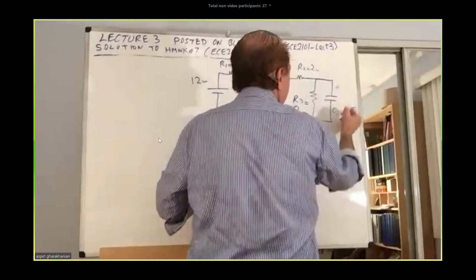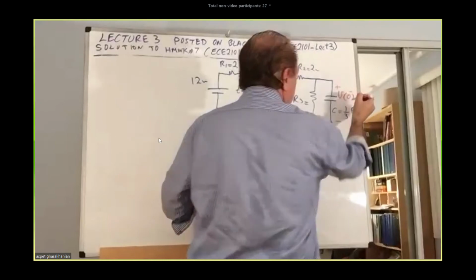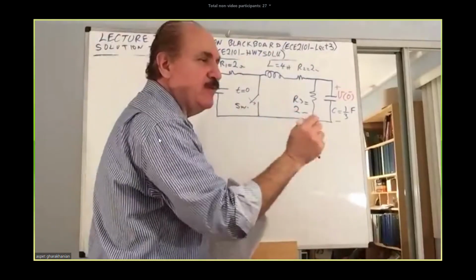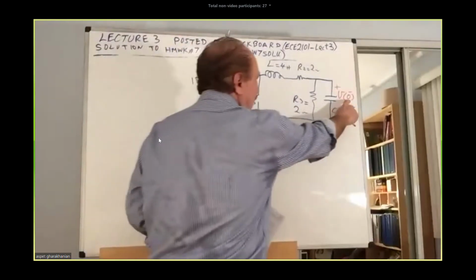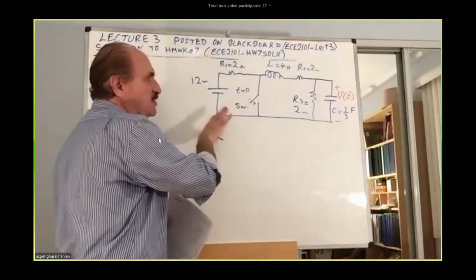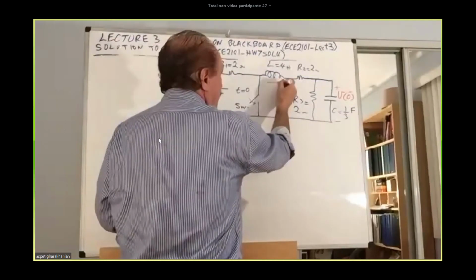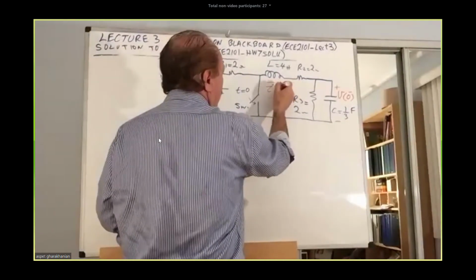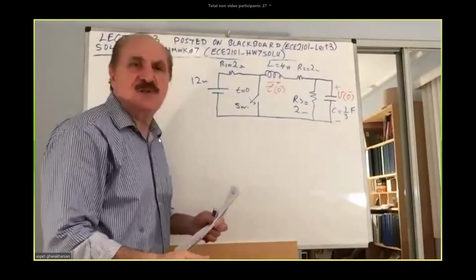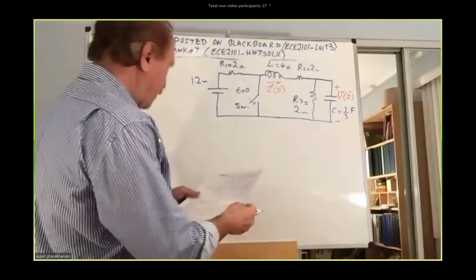Plus minus V of 0 minus. I can deduce that amount while it is open, only a moment before closing. So 0 minus means just before closing this. So the steady state condition is still holding. There must be a current going through the inductor just before closure of that switch. We can predict it from simply circuit inspection. So here's how to inspect. Step 1.